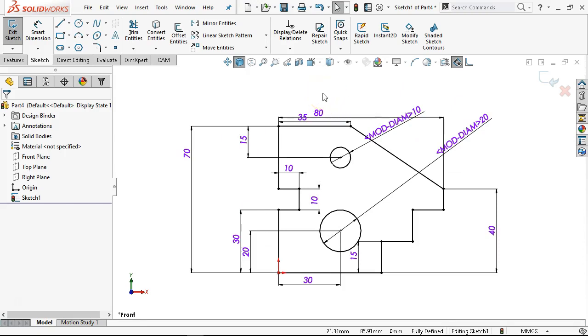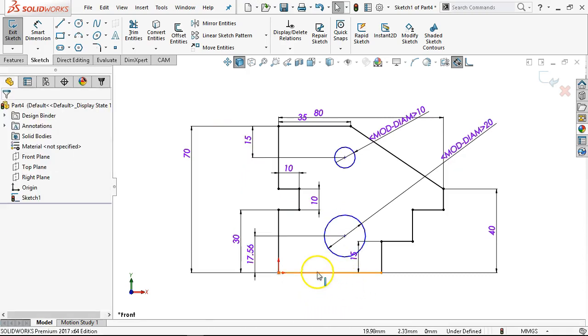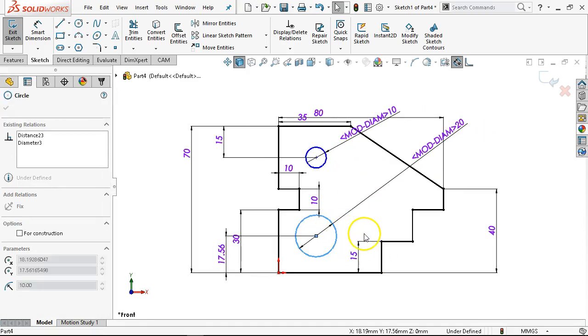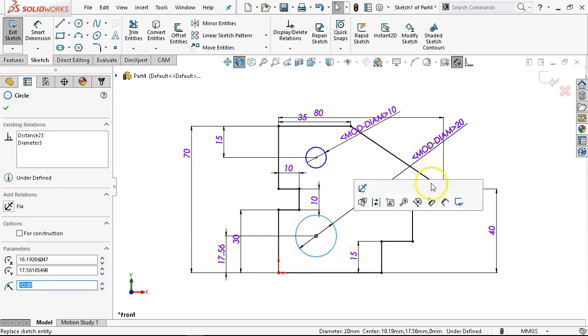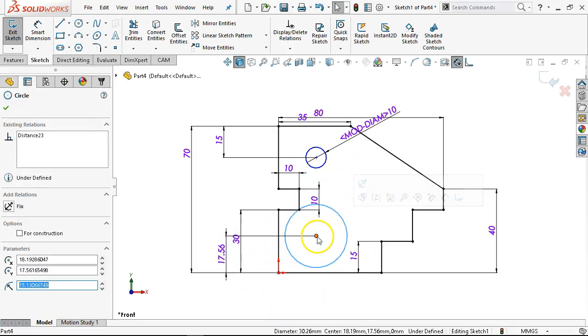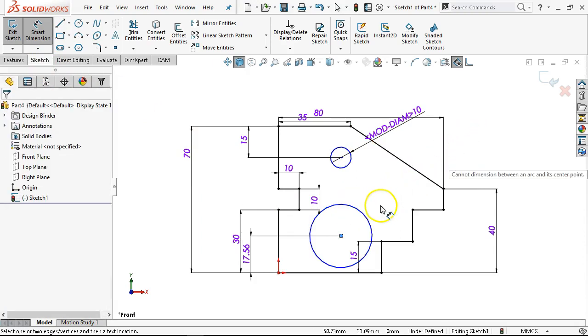So what you'll find is that chase, that game of getting it fully defined, is you're coming down to one or two items. So let's just go ahead and do the Control Z. And if I were to pick these, so grabbing the center point, even the circle is going to give me some information. If I grab the circle and nothing happens, it's not the diameter. We have a diameter dimension. If the diameter dimension wasn't there, then I would see my circle get bigger and smaller, and I would be able to see its location change as well. Since that one's moving with it, it's another piece of the puzzle giving me some information back to work from.